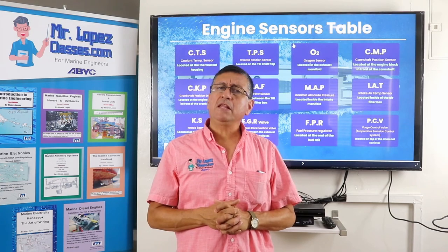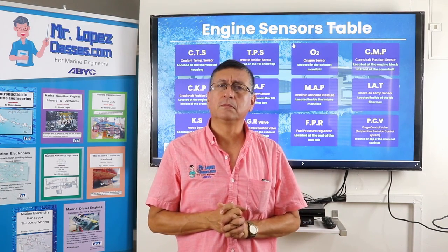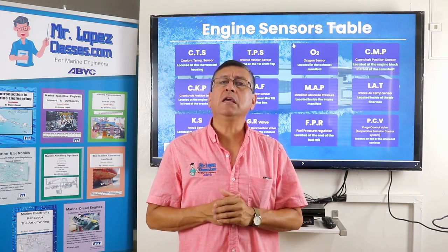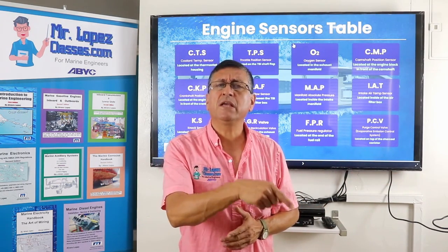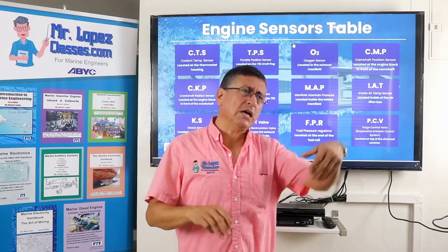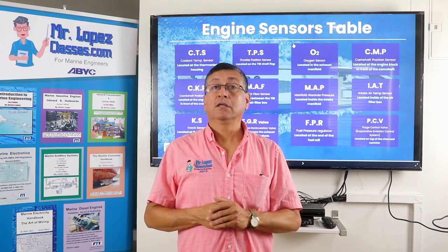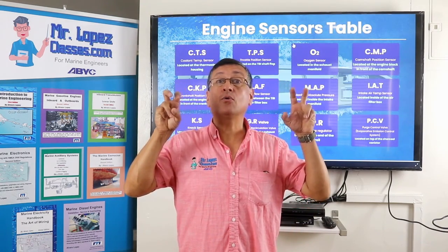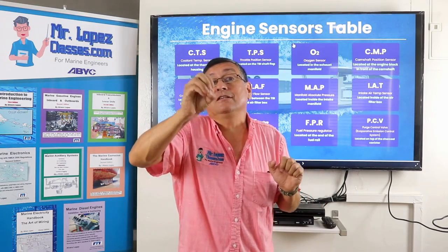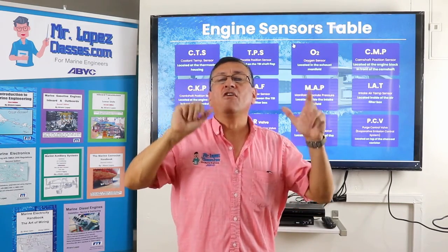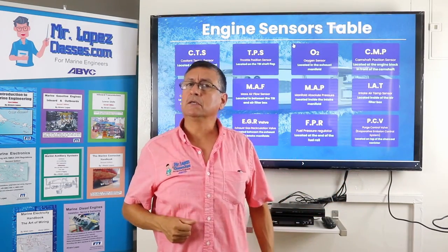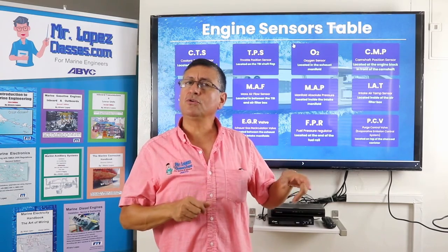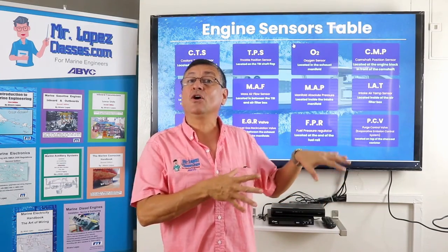Yes, because probably the problem is not in the sensor. Probably the problem is a mechanical problem in the engine. How many times did you replace the sensor? Oh, I replaced the sensor 3 times and the code continues. The problem is not the sensor. The computer reads oxygen sensor because this is the element that reads the inconvenience, but the problem is in another place. You need to analyze the mixture, the temperature, and other parameters.